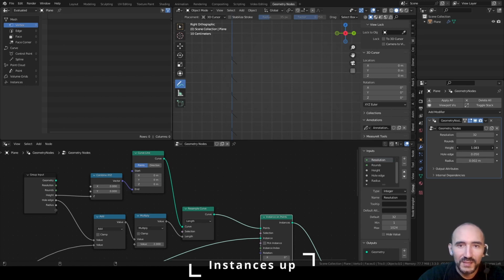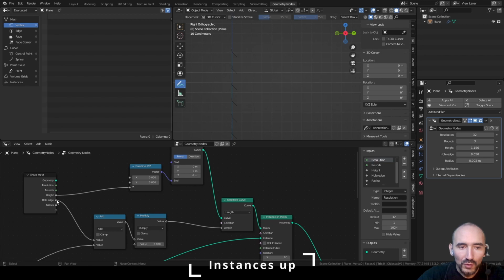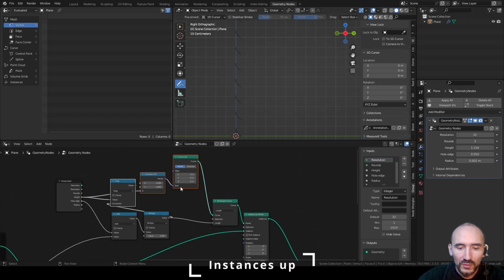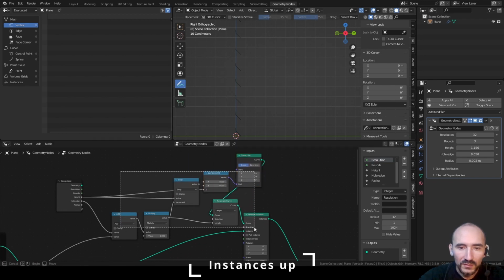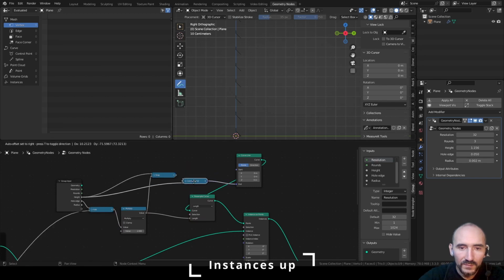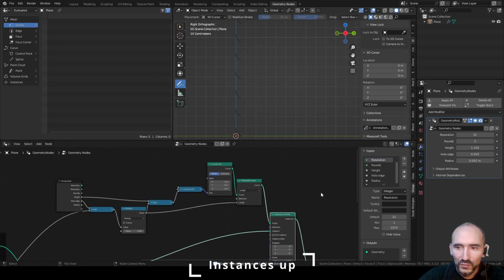So to avoid this behavior, we can simply snap the curve height by this little height. We can link these to the snap mathematical function and use this single length or height, this piece of height, to have a correct value here. So I can move this a little bit, snap, combine, and use this as the z factor, resample the curve and instance as we want. And now if I decrease, we have a correct number of pieces shown.